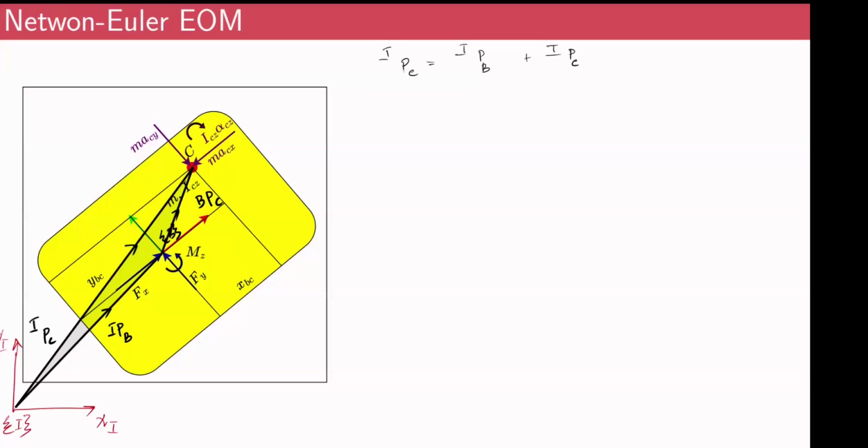It's a static quantity, a constant, or a fixed quantity. But this will always be different. If the mobile robot goes someplace else, this quantity is going to change. So what we can do is write it as the position vector of C with respect to B, and then using a rotation matrix, we can bring it to frame I: the rotation matrix of B with respect to I, where this rotation matrix defines the orientation of this body fixed frame B with respect to the initial frame I, right? So I'll label this as equation 1.